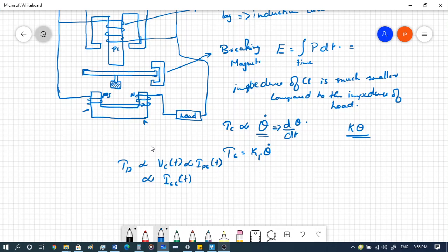So now we know that there is a phase difference between the voltage in the pressure coil and the current in the current coil. So the deflecting torque can be written as the current I into the voltage that is applied into the cos of the phase difference, cos phi.